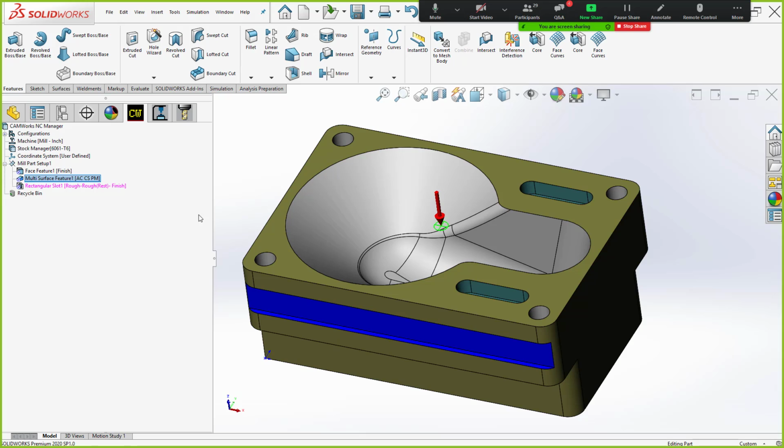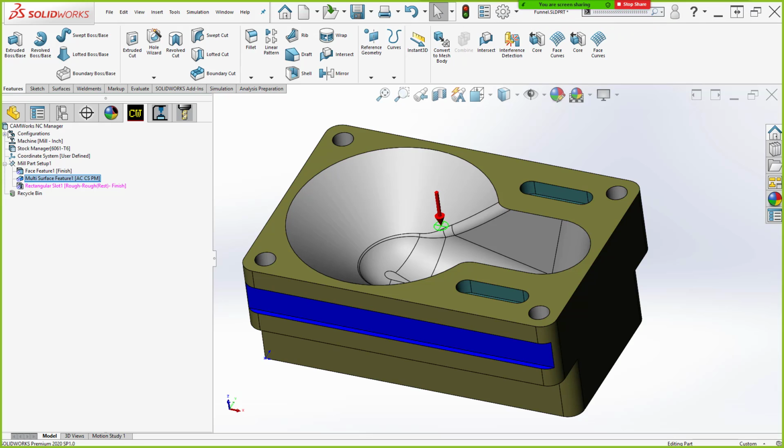If I use configs for fixtures, does CAM respect the config name? Yeah, so you have to have SolidWorks CAM Professional or higher. That's the second package level up, the first one you pay for, past Standard. Configurations treat it as if it's almost an entirely different part file, but it's not a different part file, right? So my point is that you're basically starting from scratch again. All your CAM stuff will start from scratch.